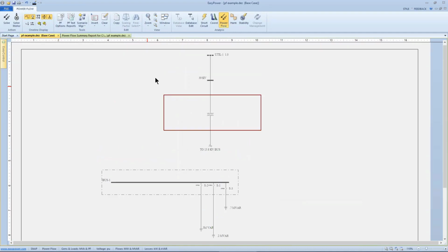Now what I want to do is run PowerFlow. So if I run PowerFlow, there's my power factor. Here's my capacitors, and I can do these operations. I just put in a half a megavar capacitor, and I brought my power factor up to 0.913, which is not bad. I have also the ability to do it 0.2. I get 0.836.